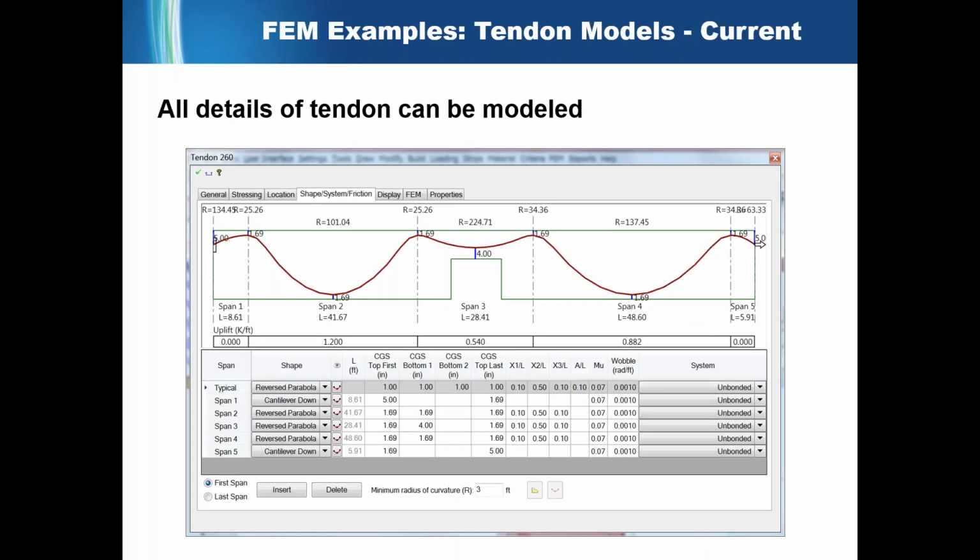And when you're modeling these tendons, these are true construction elements. So they are modeled from end to end, and they have a lot of information stored with each one. For example, in this tendon, and those of you who are used to Adapt PT-RC might find this image somewhat familiar. It is kind of a duplicate in some ways, but it's important to note what's shown here. You can see that this end has a dead end, whereas this side is a live stressing end. You can see the CG values indicated.